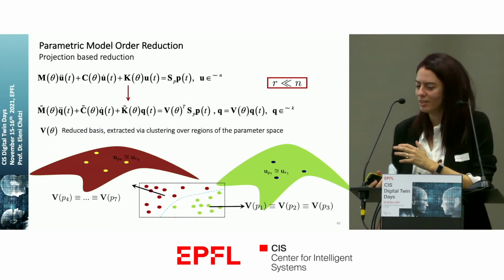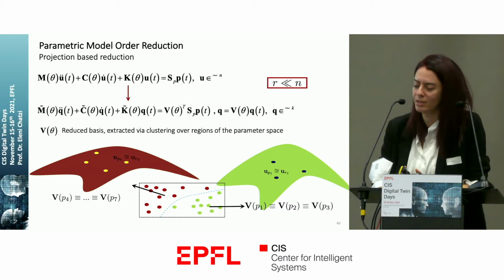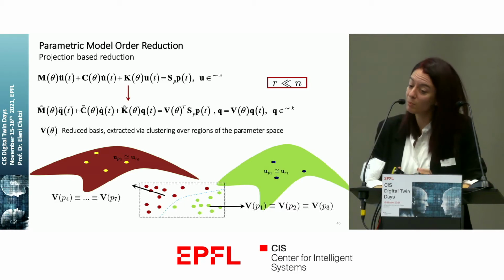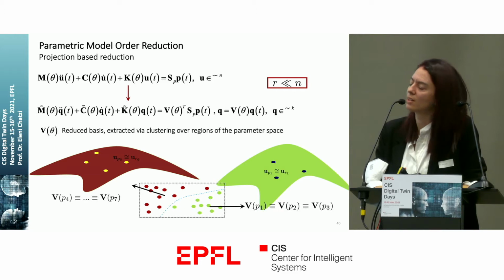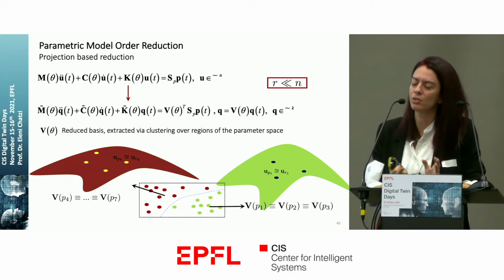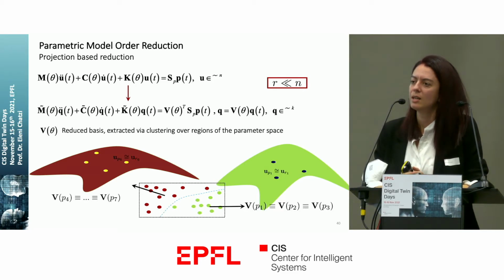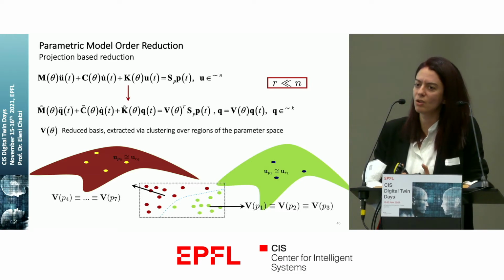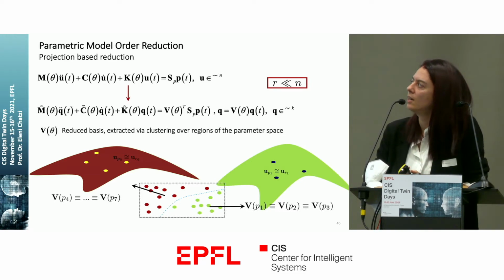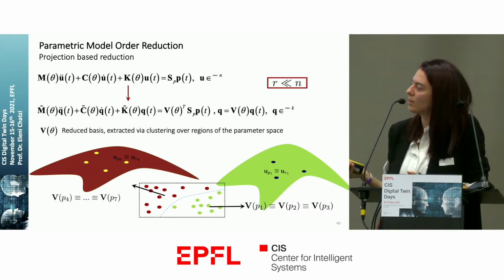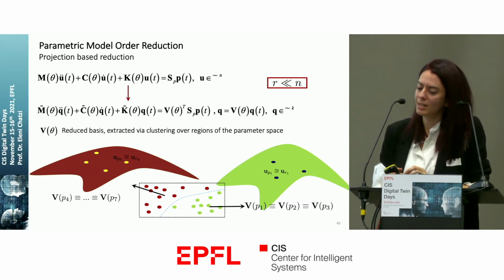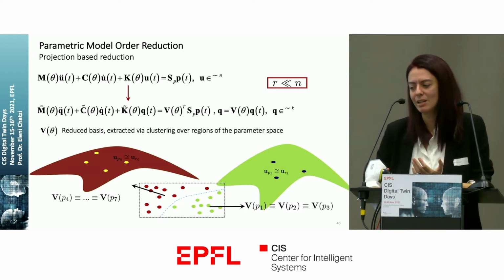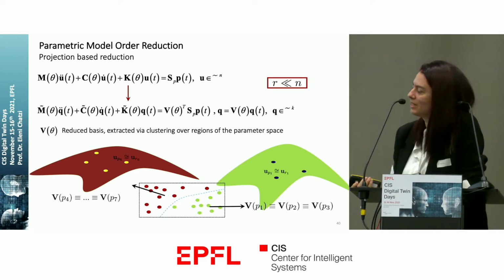The challenge here, well, I would try to follow exactly what I showed you before, the physics-based reduction approach that is parameterized again. And now my parameters are the characteristics of that crack, the location, the orientation, the positioning of the crack. But now the problem is that the underlying problem that I'm trying to solve is actually highly non-smooth. It's no longer a smooth, maybe nonlinear system. Depending on where your crack is located in that medium, you can get highly different reduction spaces, which makes this problem of parametric reduced order modeling non-trivial.